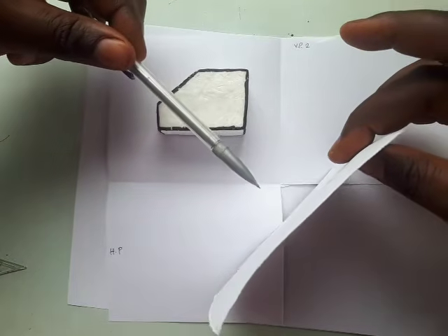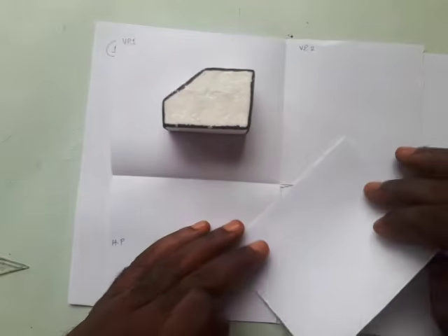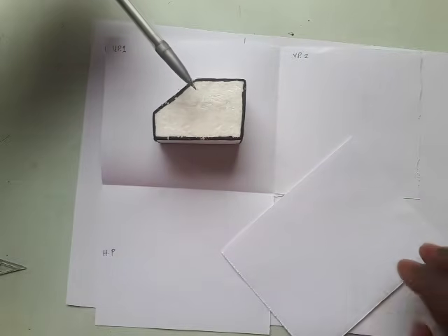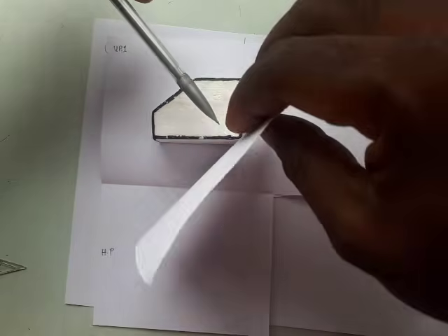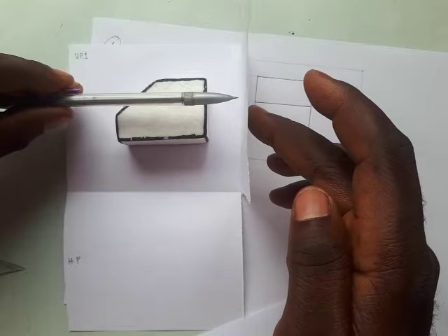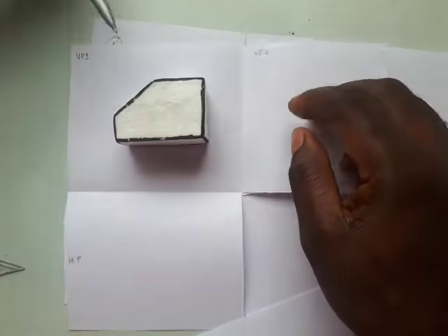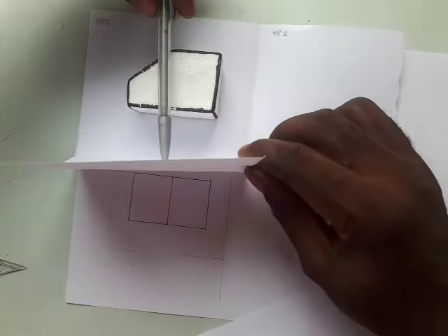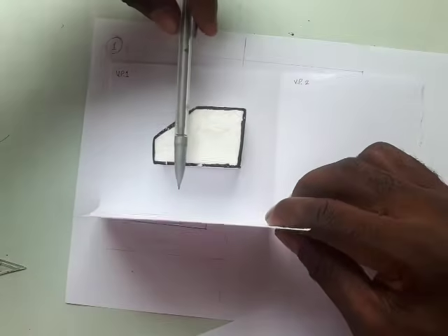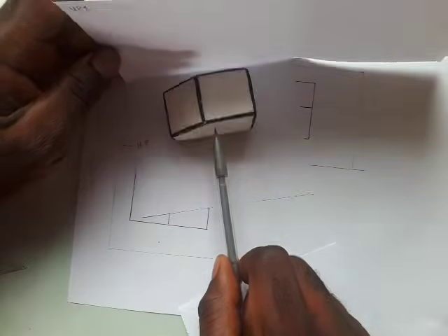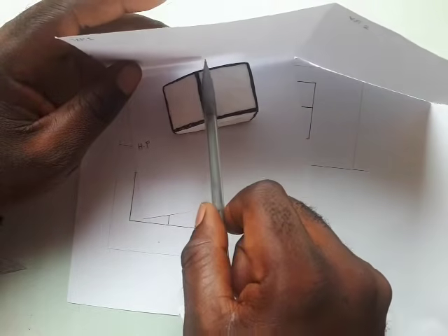You see this plane now, that is where I'm going to draw my auxiliary view. Whatever view I am seeing in this form, I need to create a plane perpendicular to it. Remember, in this view, which is plan, this plane is perpendicular to it, as you can see. Same as this view. Let me go back. If I'm viewing like this, it is perpendicular to this plane.